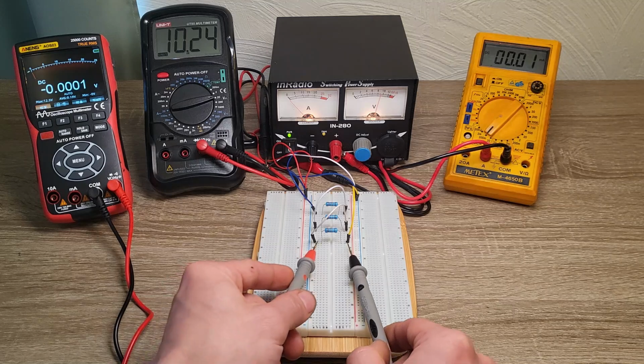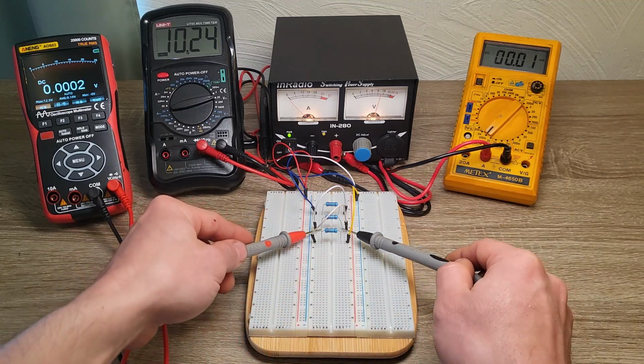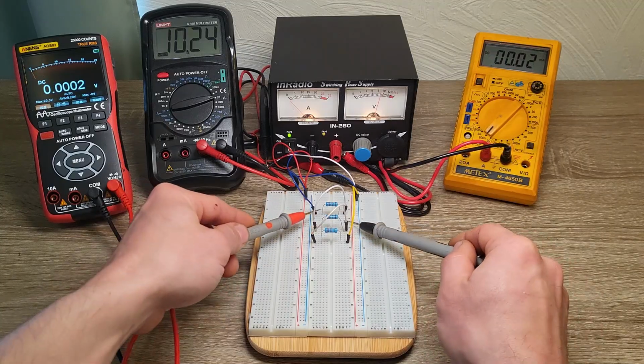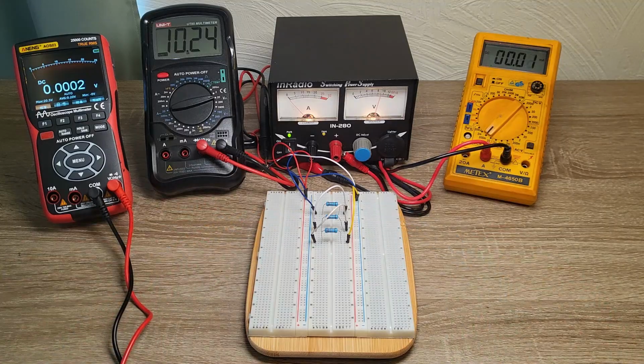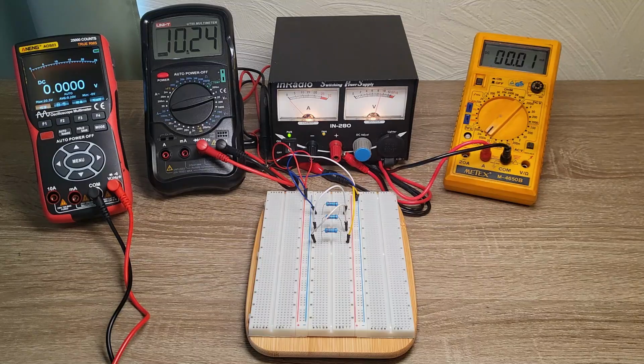Let's measure a voltage drop. Now it equals 3.3 on the first one, 3.34 on the second one, on the third one 3.43 volt. So we can also measure that the flowing current should be around 15 milliamps right now in this circuit.